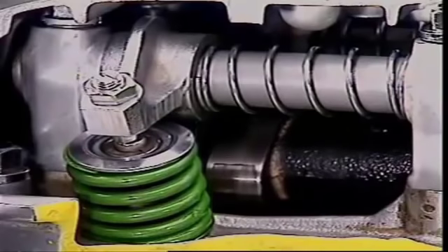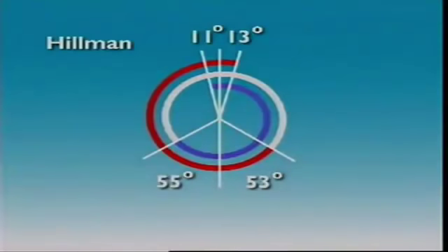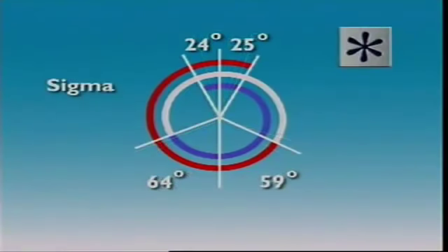The cam lobe performs three jobs. It opens a valve at the proper time and gives it proper lift. It lets it stay open for a sufficient time. Then it lets it close at the proper time. Accurate valve timing is crucial. Valve timing can vary from engine to engine, as set out in manufacturer's specifications in the valve timing diagram. The shape of the cam is called the cam profile or contour.